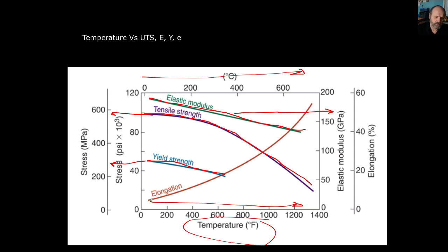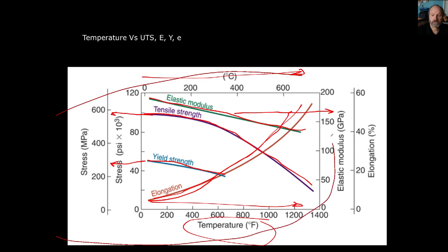So and also the elongation, it stretches a lot easier, okay? The elongation goes up for a given stress, so the elongation, which is related to strain, of course, how much you've stretched it by, increases with increasing temperature. And this all makes sense. So if I were to give you a graphic like this on your exam, and then you had to maybe match which is which, right? You would be able to do that.